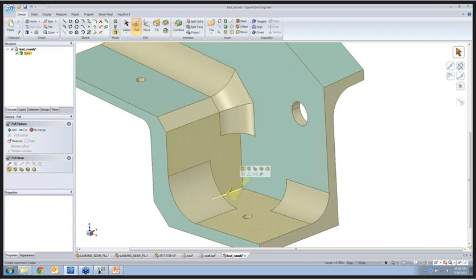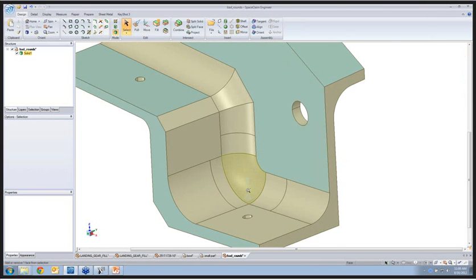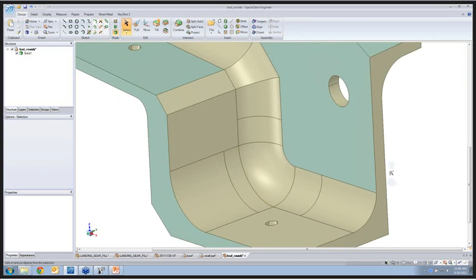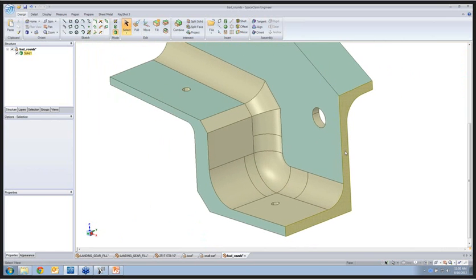Well, it's all done with the pull tool, right? The default behavior is to make rounds. So now when I click on edges, using this up to option to reference existing ones, in a matter of seconds, I'm able to put that junction right back in there, that sphere in there, and look at my edges. They're all connected together. It's one clean, smooth edge. Now you won't have any problems with your toolpath. So that's one way. It's just a different way to get rid of problem areas and replace them.